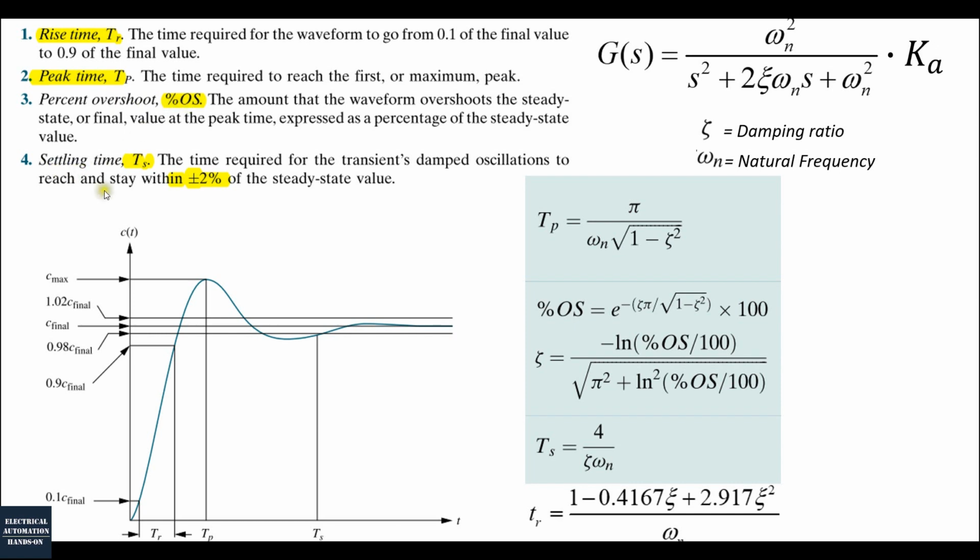And finally, another important one is the settling time, the TS here. Take care, in this picture it is using TS. When the system reaches the 98% of the settling status, within plus and minus 2% of the steady state value, then we see the system has reached the settled status, and we can write down the time. In the real practice field, since the system always comes with noise, sometimes it's hard to calculate the TS.